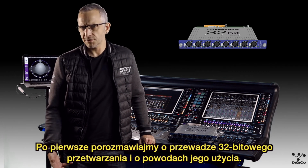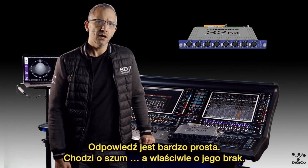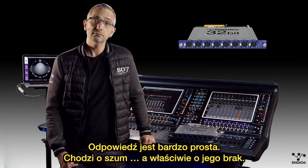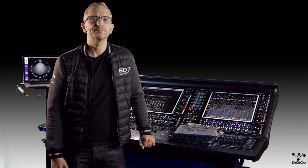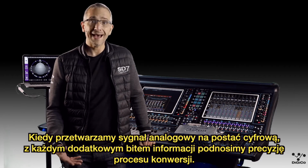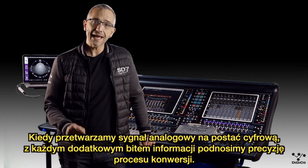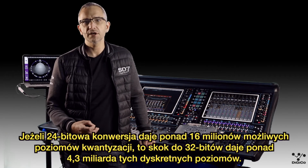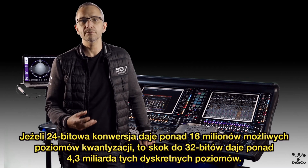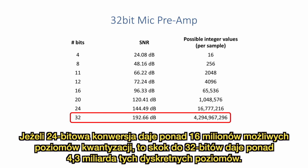And first up, let's talk about the advantages of 32-bit conversion and why we do it. And the answer to this is really quite simple. It's all about noise, and more specifically, the lack of noise. When converting from analog to digital, with each additional bit of information, we increase the accuracy of the conversion process. So while 24-bit conversion gives us over 16 million possible quantization steps, the jump up to 32-bit pushes the number of steps up to 4.3 billion.